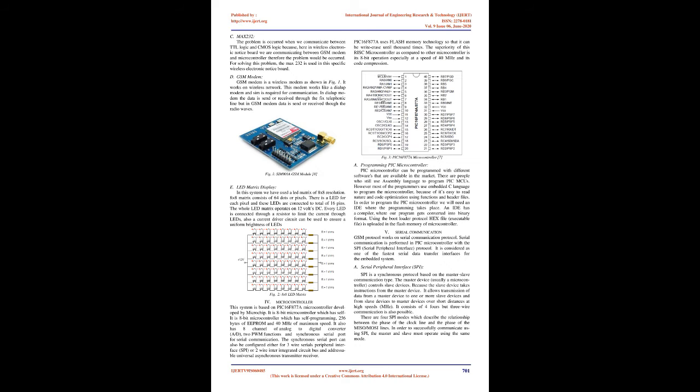C. MAX232. A problem occurs when we communicate between TTL logic and CMOS logic because, here in the wireless electronic notice board, we are communicating between the GSM modem and the microcontroller. For solving this problem, the MAX232 is used in this specific wireless electronic notice board.